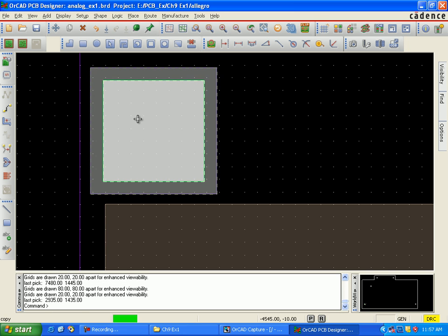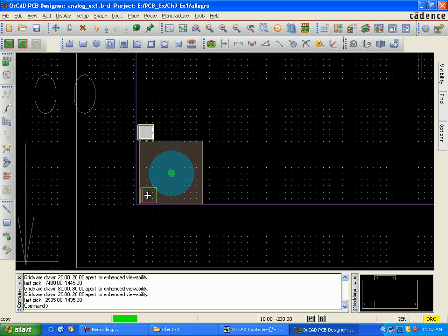Make sure it comes in the row of the grid, not overlapping anyone. Otherwise a DRC error will come into the picture. Do not let it overlap.